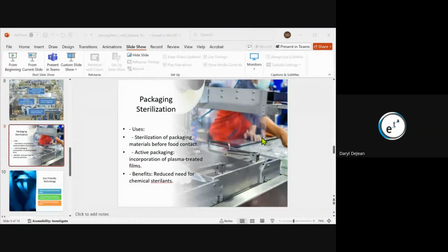So, sterilization and packaging. This is done quite frequently, mainly in bottling operations. A lot of people have the wet cleaning of bottles and those kinds of things. We're actually pumping in some of the non-thermal plasma through an air system where the bottle's inverted. You pump it in, it flips over, goes and gets filled, and that treatment is inside the bottle, keeping the product fresh and clean. We've been doing studies in a couple different types of bottling operations where the impact of yeast in the air is getting sucked into the bottle itself and affecting the product.